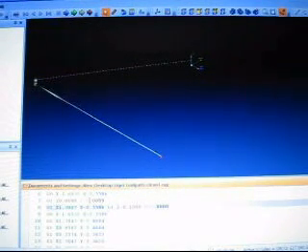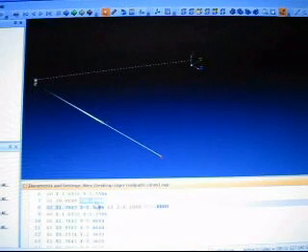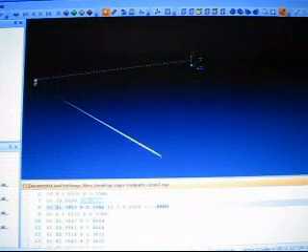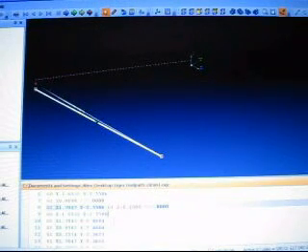So this is what we thought was going to be a plunge in the previous operation, all the way down to minus 0.4 of an inch. It has a plunge feed of 20, but that could just be rapid as far as I'm concerned right now. I'm going to leave it where it is. It doesn't really matter because we're off the part anyway. So it could be a rapid if you were playing it risky. If you're a daring CNC machinist, you might want to put a rapid motion in there. But I'm not going to risk life and limb over it.